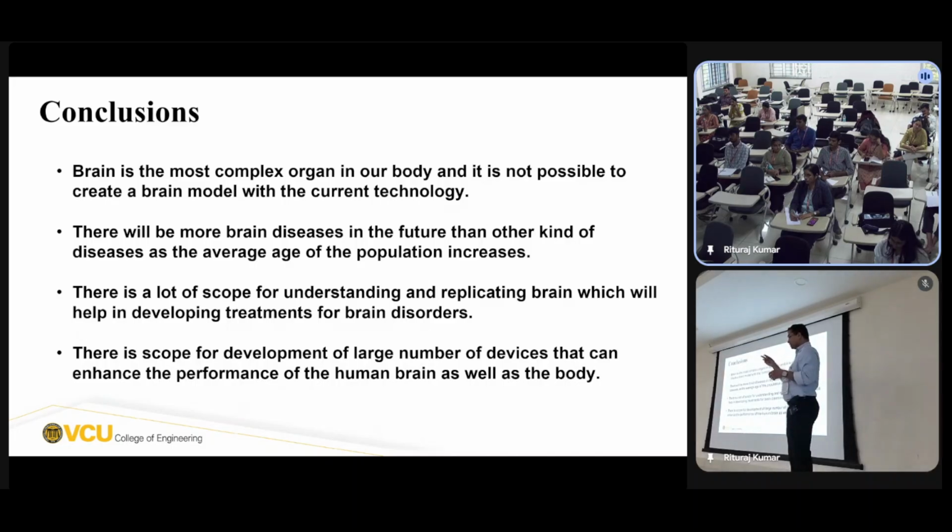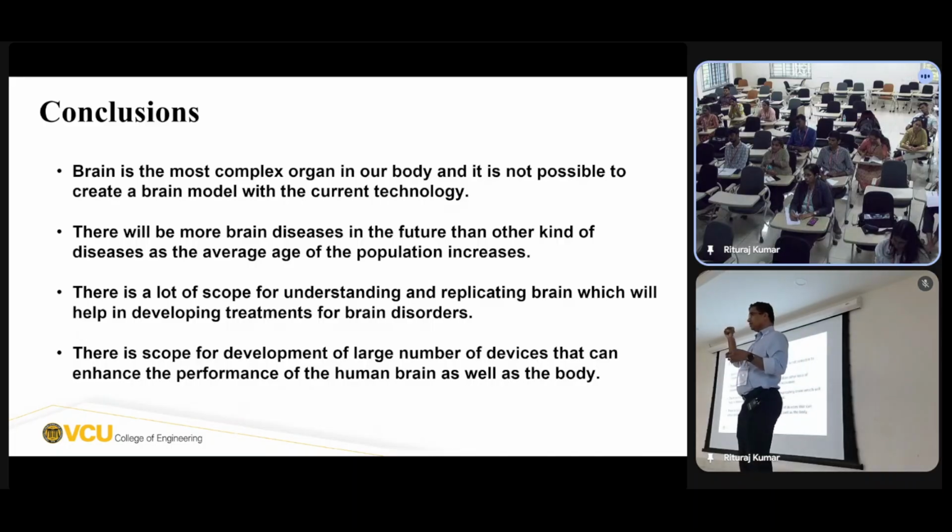So if you have a nanoparticle and you have a core shell where the core is magnetostrictive material and shell is piezoelectric material, okay? So you apply magnetic field outside the head and make the core oscillate, right? That makes the shell oscillate, but shell is piezoelectric. And when the shell oscillates, it generates voltage.